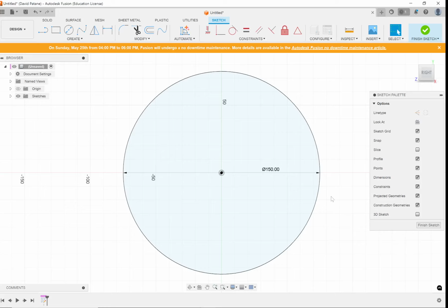But it's as accurate as the CAD software would let this be, which for most modern CAD softwares is as accurate as drawing. But it's not infinitely accurate. It still has to get that data into a computer, whatever number system the computer's using, which is only accurate to a certain decimal place. So you will get artifacts that come out of your particular CAD drawing. If you have two lines that we know overlap, depending on how they're drawn in the CAD software, they might be some minute distance apart, which could cause issues when it comes to selecting a shape.